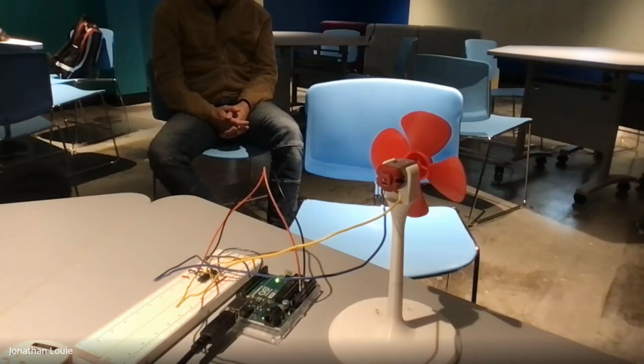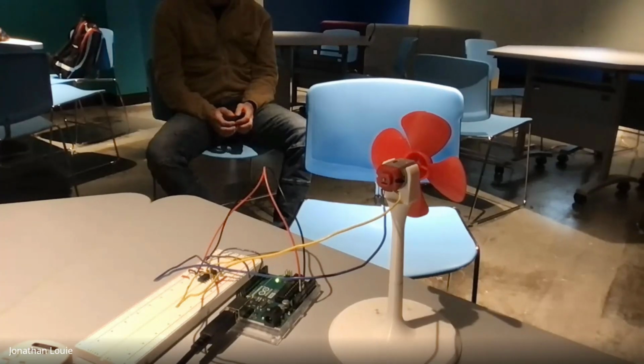Another aspect to consider is the actual physical requirements or constraints of the device you're building. So say you need a temperature sensor for sensing the outdoor temperature. You might not put that directly on the circuit board right next to the CPU, because it gets hot and it will throw off your reading. Yep, there's lots of physical constraints. That would be a good one.